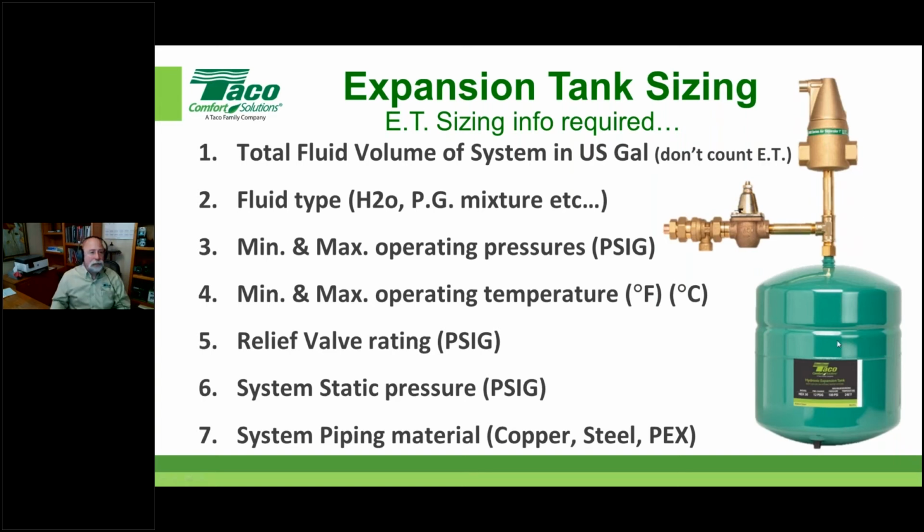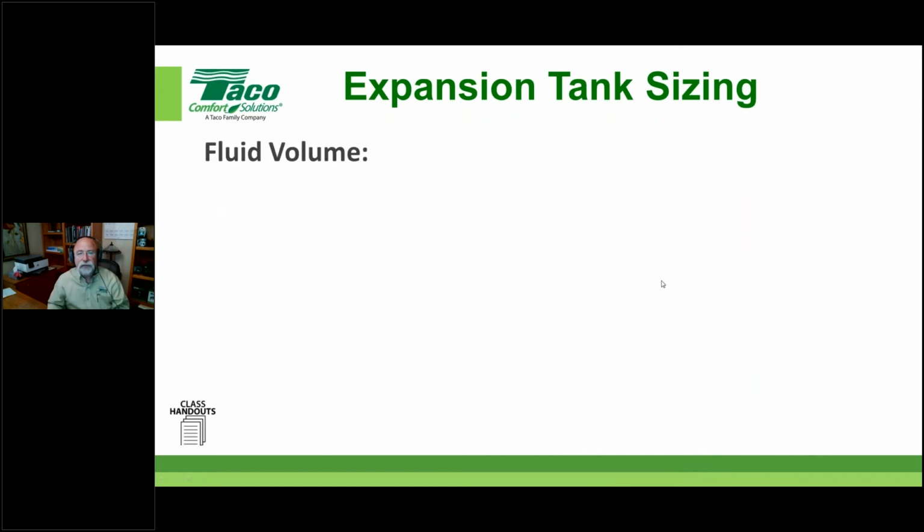I didn't know it at all, didn't see the gauge change that much. So I know for a fact that the expansion of my fluid was being absorbed in the plastic pipe that was exposed. This plastic pipe wasn't embedded in concrete or anything like that. It was all open to atmosphere. It was one of those remodel type projects. So John knows where I'm going with that. But I guarantee you the type of material you have has an impact on the required size of the expansion tank. Anyway, just a heads up.